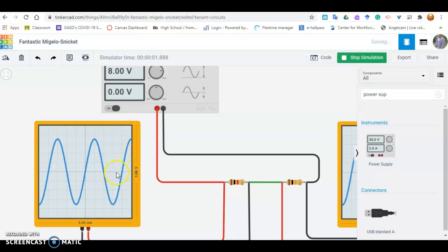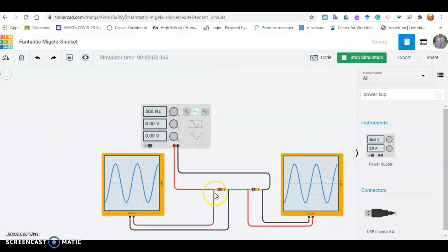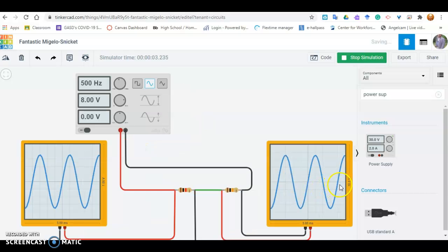So when you split out from the middle here and you're trying to count a peak voltage, you're counting 1 square, 2 squares, 3 squares. It looks like maybe 3.5 squares, or perhaps a little more, just about 3.5 squares. Double that for your peak-to-peak voltage. That's going to be 7 squares, or 0.7 volts peak-to-peak. Okay, it's about 0.73. Now, that's across our 1K ohm resistor. When we look at our 10K ohm resistor, we're going to see 10 times that.